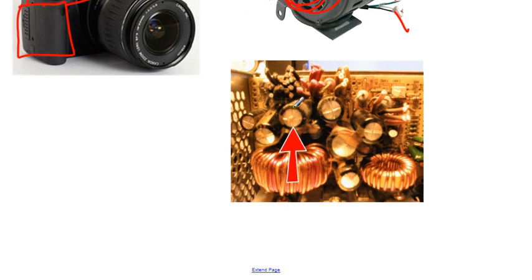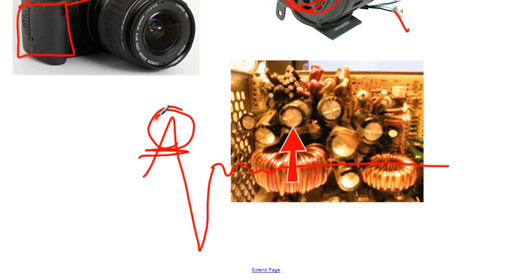Capacitors are also used in power supplies for your computer, for your laptop, for your device. These capacitors help to smooth out the voltage. It prevents there from being spikes or voltage getting too low. It stabilizes the voltage, because all of our computers and devices need a really stable voltage in order to work properly. These capacitors help to store additional charge, so it sort of cuts off that top part. But when the voltage gets too low, it can also release some energy, and it helps to stabilize it out. So those are just some of the applications that we use for capacitors.